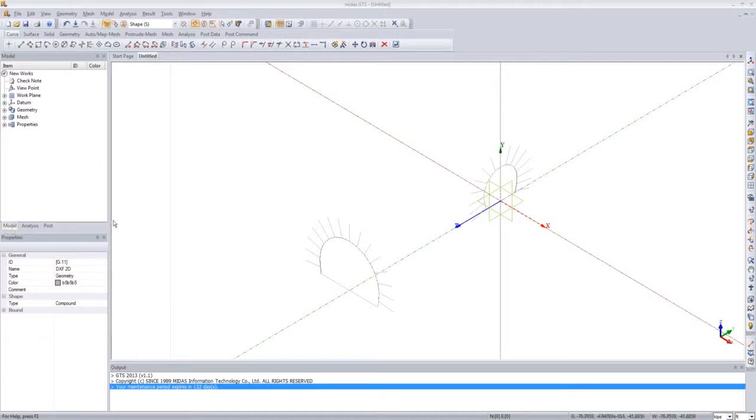Okay. As far as these lines pointing out from your arcs here, these will be our rock bolts. But for now, we're going to hide them so that we can use them later. That way, with the rock bolts hidden, it'll be easier to create our geometry. And then later on, we'll reactivate them and make them reappear. So the first thing that we need to do is explode these two geometry sets.